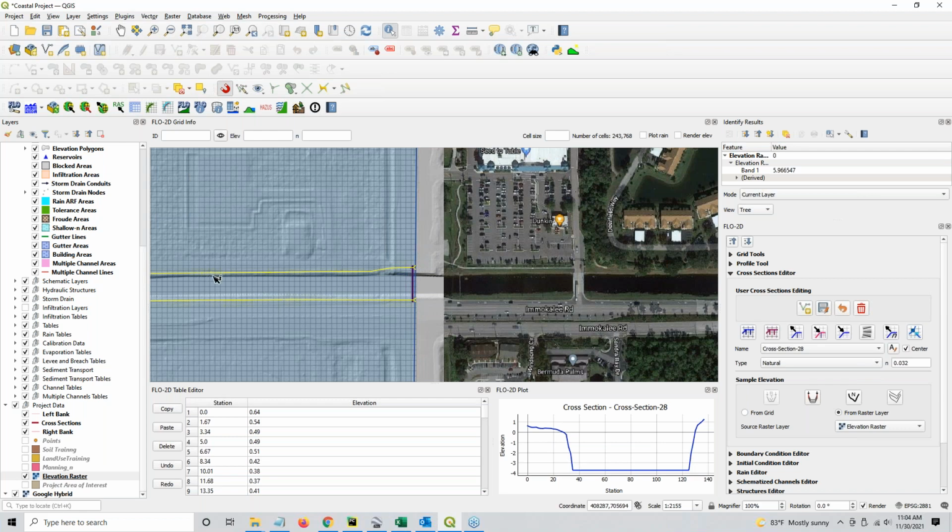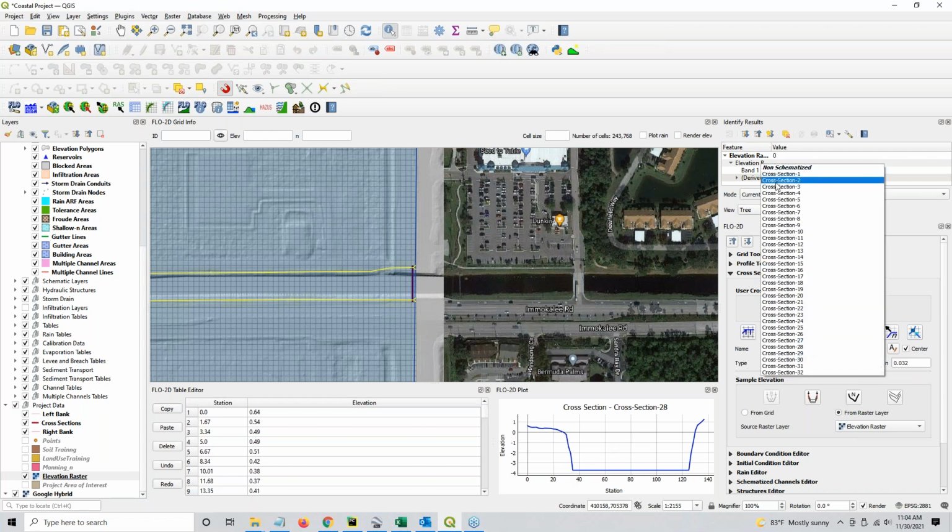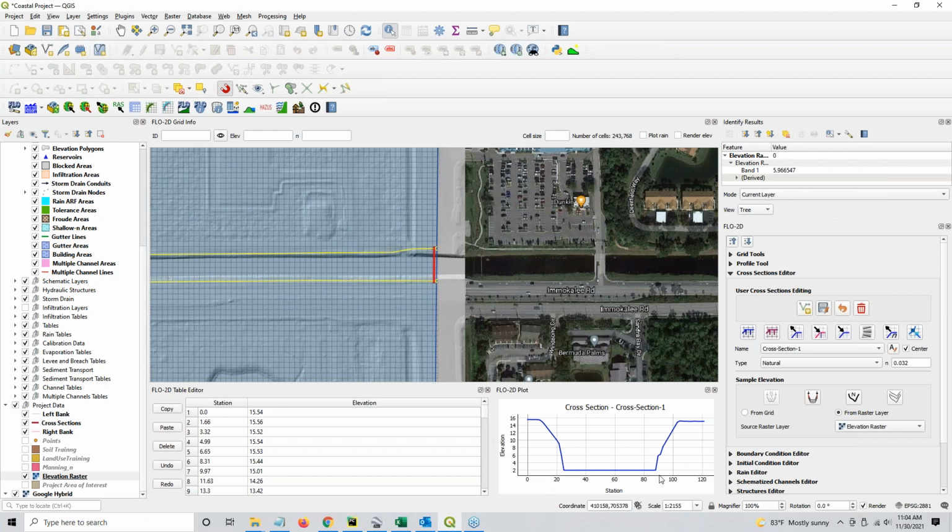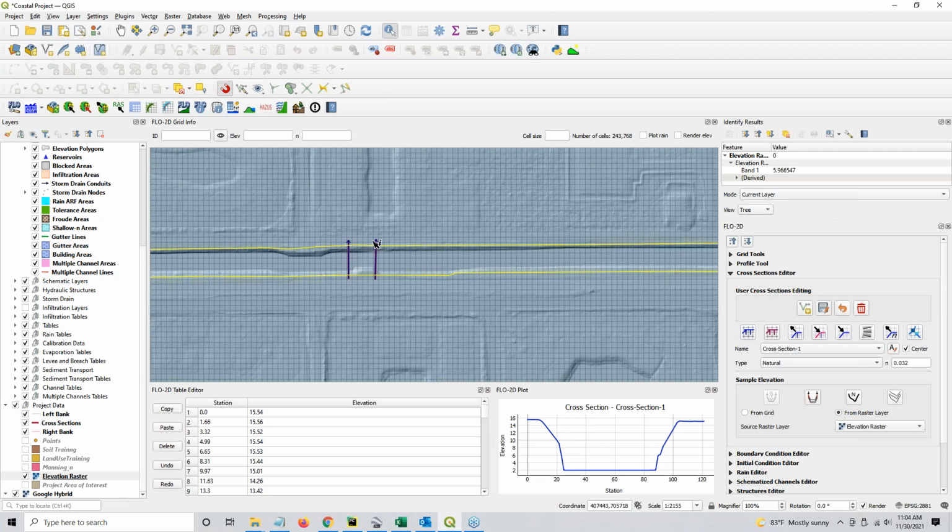And then I just estimated using the slope of the system. I take the slope of the bank and I backed out a depth, or sorry, the final depth right here. And I got my final depth was around 2 feet in elevation. And then at my weirs, I didn't really know what's going on in these weirs. So I just assumed a bit of a drop structure across this weir, and I gave it a 1/2 foot drop structure. So you can see that when we open this channel up in the profile,